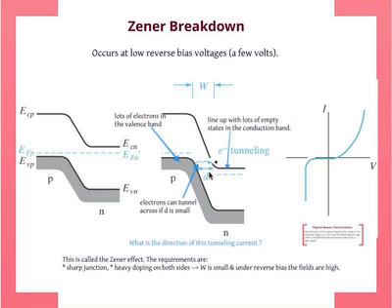And of course, if the electrons tunnel from the p-type to the n-type, it's the reverse bias current, right? The current is in the opposite direction, n to p. And that's what's called the Zener breakdown. And the fact that the current can get very large is because there are lots and lots of electrons here, they're filled bands. Lots and lots of free states here because of the conduction band. So lots and lots of exchange can happen. Okay?